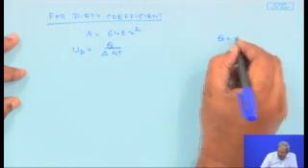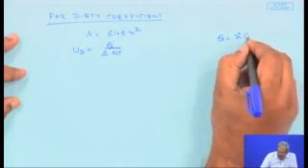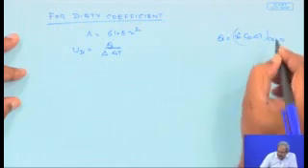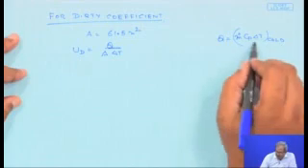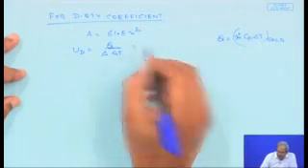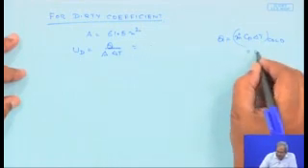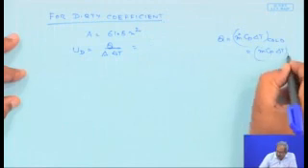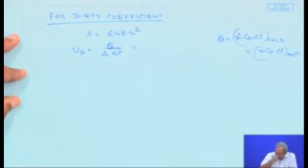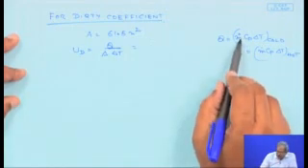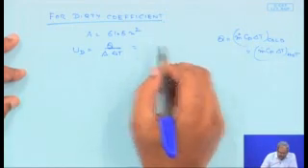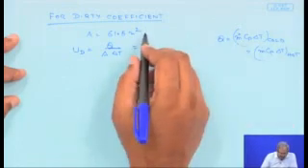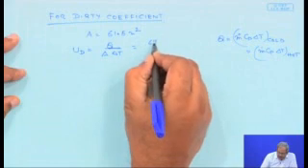and Q is simply m dot Cp delta T for the cold as well as for the hot, but we are going to use the cold over here. It does not matter. So this must be equal to m dot Cp delta T for the hot side as well. So we are using the cold side in this specific case, but you could have used the hot side as well. So m dot of the cold side fluid, which is